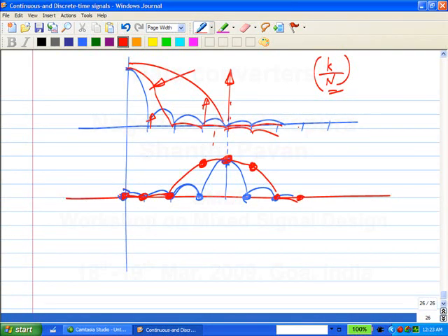So this means that the resolution is limited. With the rectangular window, in the best case, you can place sinusoids in 2 bins next to each other and distinguish between them, whereas with the Hann window, that's not possible. Okay? So any questions on this?